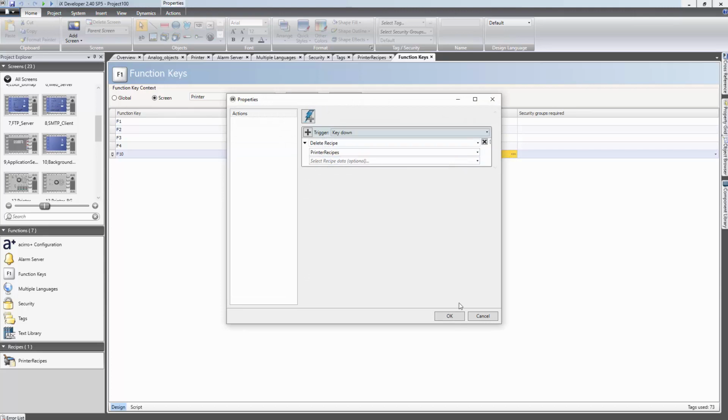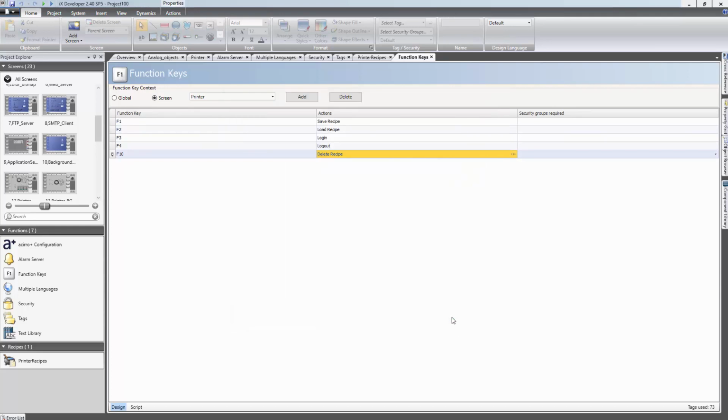These are a few examples of necessary actions after a conversion. You will need to review the log file and correct all of the necessary warnings and errors. It's always recommended to download the application to the target and verify the functionality as well as the graphical appearance before making any further adjustments of object size or placement in iX Developer.